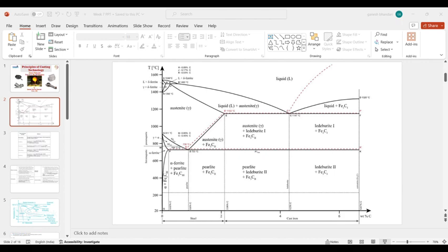This process involves heating steel to a temperature just below the lower critical temperature. So we are not going above the lower critical temperature; we are remaining below it, that is 723 degrees Celsius. Usually cold worked steel has high hardness and low ductility, making it difficult to work. We have talked about manufacturing processes like extrusion, roll forming or the cold rolling process.